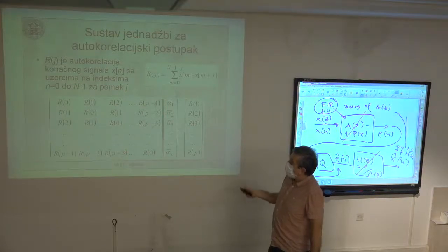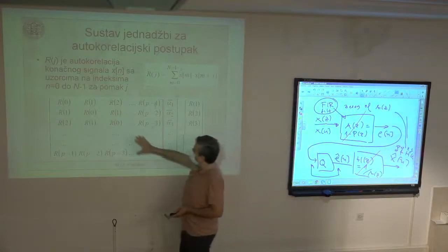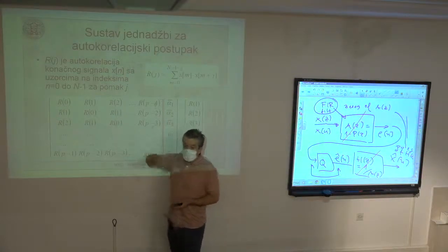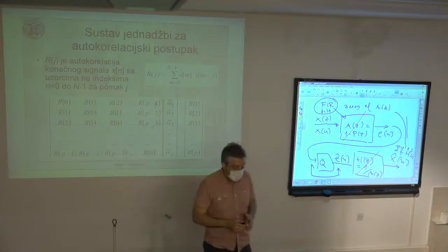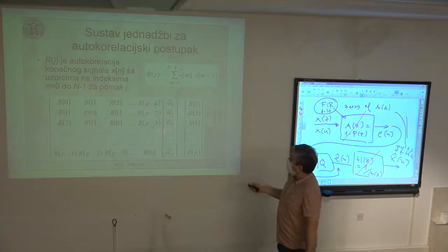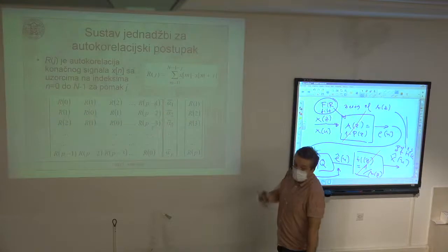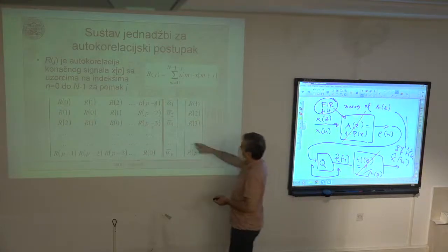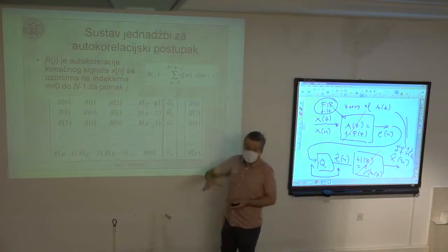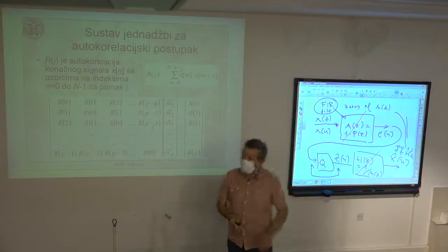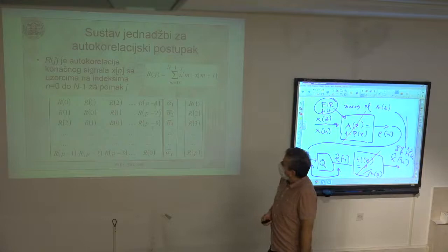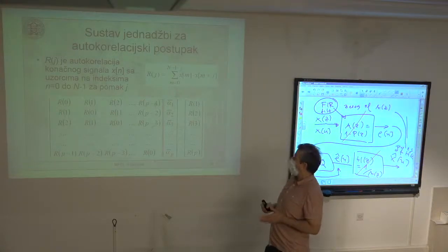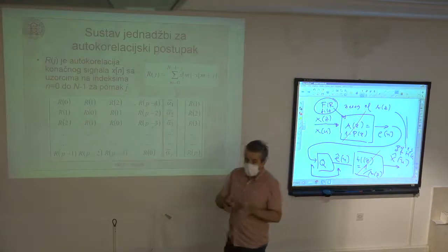But speech signal or any other media signal is not such a signal where the correlation properties are constant; they are changing. And for that reason, I have to change the predictor coefficients from time to time. I have to recompute the optimal values of the predictor. And of course, I have to somehow transmit to the receiving side what the optimal values are for this given part of the signal.